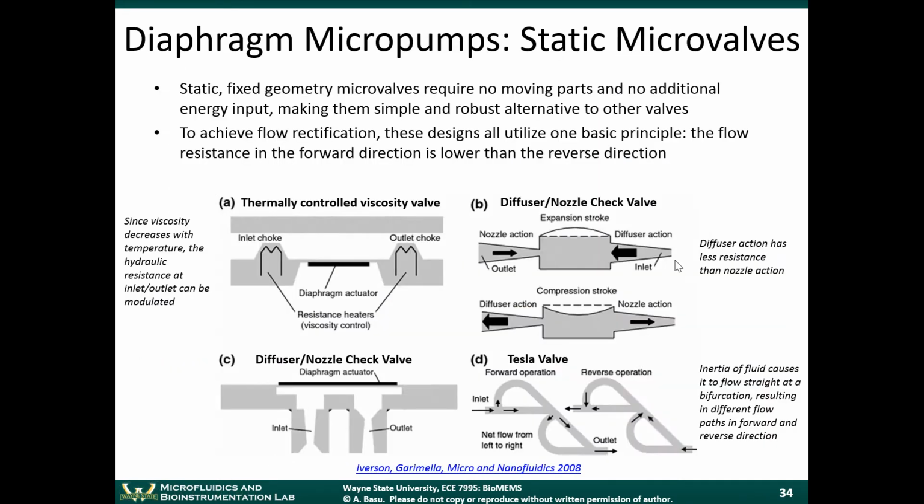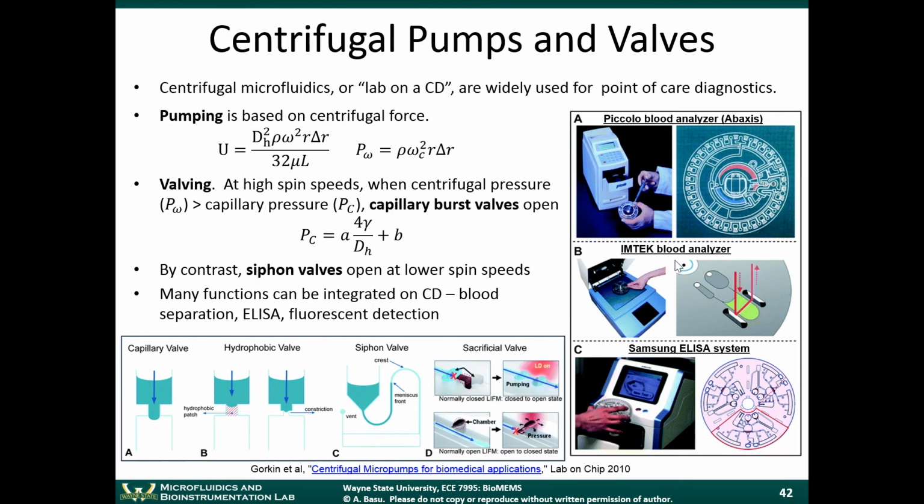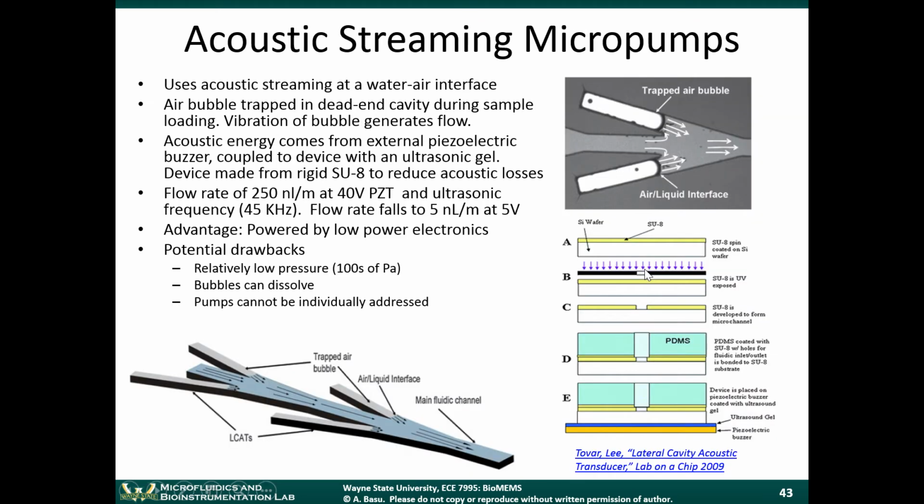So I'm going to move through this relatively quickly because I would like to really get into the separations module today. So we'll start off by talking about acoustic streaming micropumps. This was a paper that was published in 2009. Similar ideas have been proposed. One of them we saw in the mixer chapter, when we said if you take an air bubble, you trap it in the channel, and then you apply an acoustic vibration to the entire system, you will get something called acoustic streaming that occurs at the air-water interface.